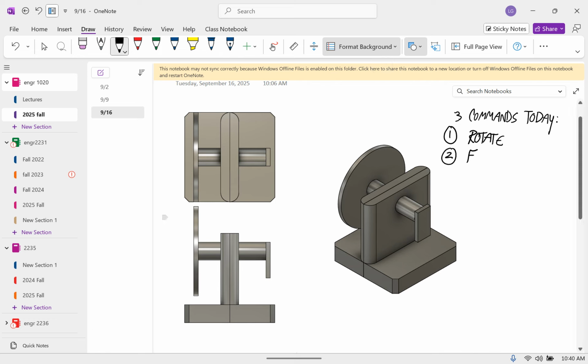The first one is fillet, it's spelled like fillet, so a fillet is like, you can see that these edges here are rounded. Okay, you can do that. There's a couple of reasons to do that. I mean, one is that aesthetically you want something rounded, but also often rounded connections at edges distribute stress better, and so it makes the parts stronger. So that's a fillet, the rounded ones.